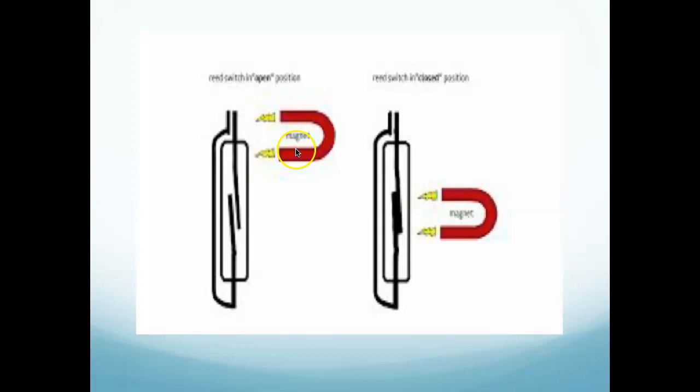The magnet, however, has to be a certain pull, and it has to be a certain orientation. If you think about the magnets, if you turn a magnet the other direction, then it will push things apart. If you have the magnet slightly held up or down or far enough away, it will change the amount of pull. The magnets get balanced based on the distance, and the magnets themselves are matched as a pair, and they have to be equal distance apart. And if you try to use another magnet, you're probably going to have too much pull, which it will detect, or too little pull, which will open it up. So they really are harder to defeat. People talk about, well, they're magnetic switches, so I can just shove a magnet between the two. It's going to hold the reeds in this position.